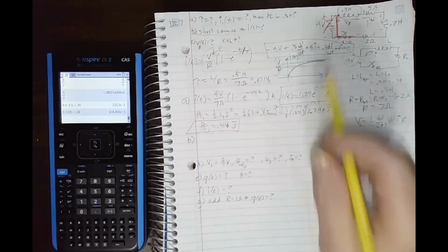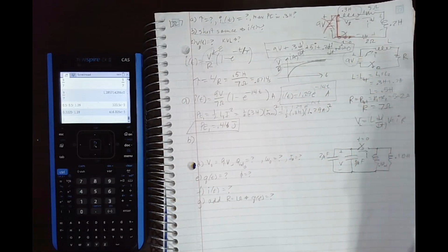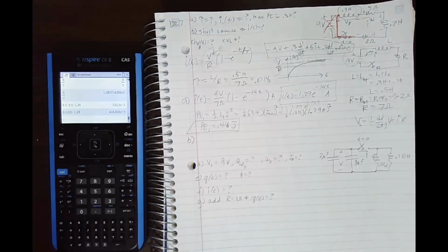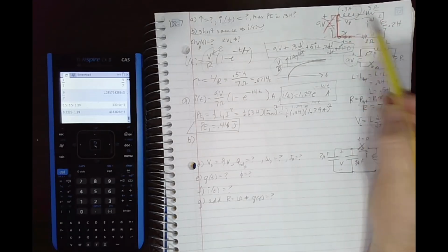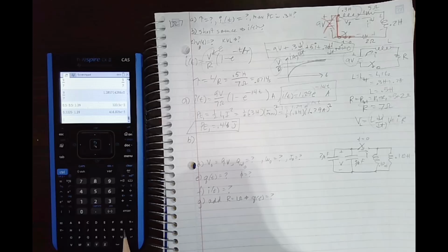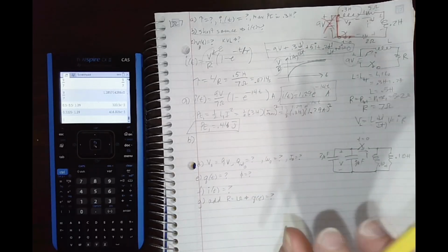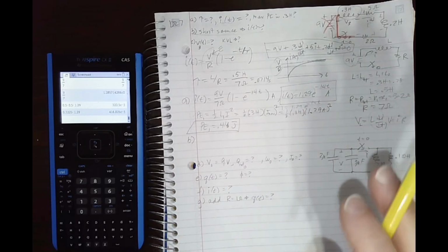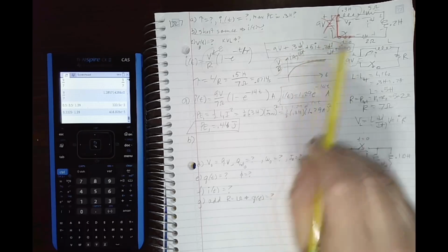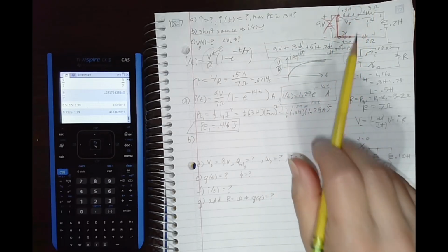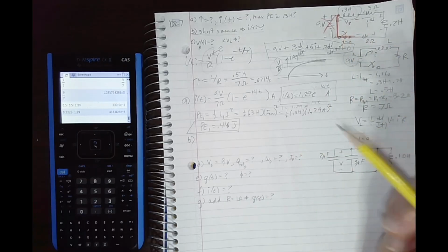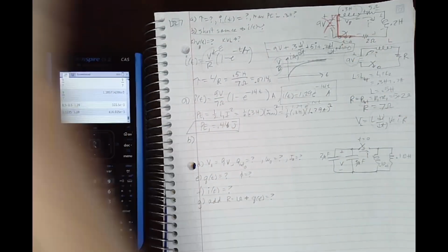So we reach this maximum current, and then we suddenly take the source out. If the source hadn't been in there for a long time, there would be no current. Nothing would be happening because the resistors would dissipate all the energy that the inductors might have had, so we would have no current, right? But at this point, we have some current, and again, the inductors are coils. They don't like change. They're going to try to hold the current up slowly, right? So we're going to let it decay slowly.